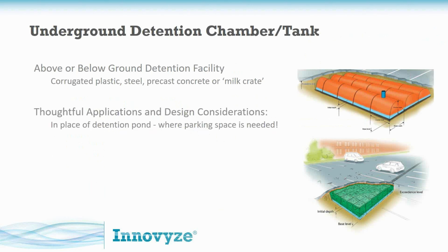So this is really, for many people, the panacea, right? If you're doing commercial development, you might have a large anchor tenant in the middle of your site. Usually you would need a pretty big detention pond or even several large clumps of rain gardens and treatment. Well, what if you can have your detention facilities underground? Well, you're going to have a lot more area for parking, and you might even be able to have another smaller tenant on that site, maybe a restaurant.